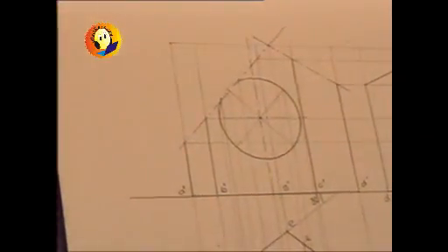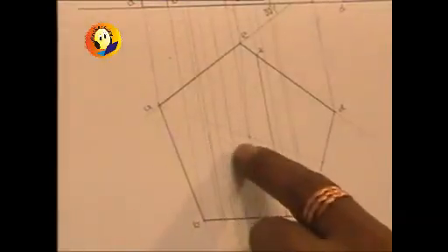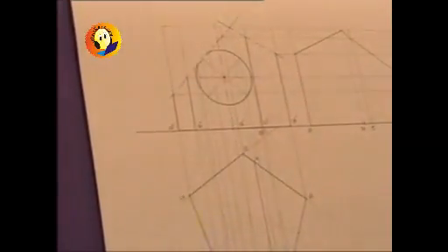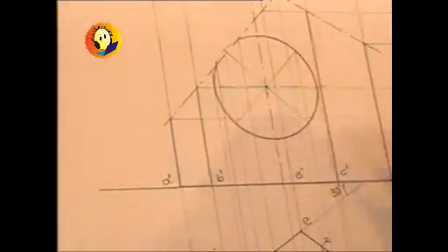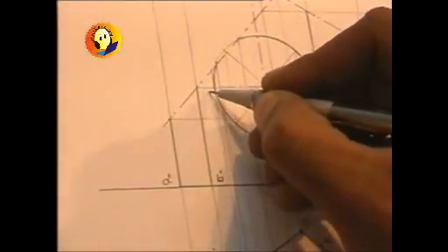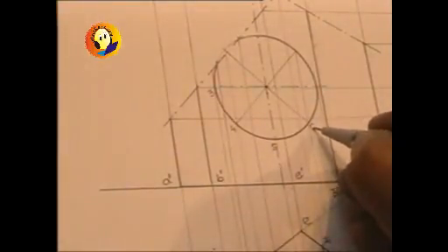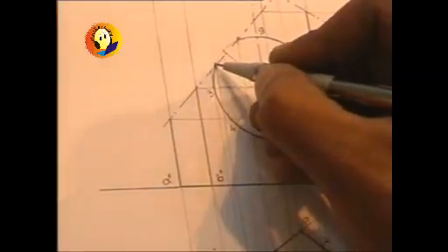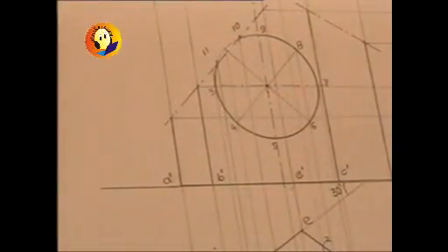And so the top view will now appear in this manner. So there will be so many points which will be coming, so many projectors which will be coming from the circle. Of course, we are required to name all the points of the circle and then name those same points even in the top view. So let us start numbering them. We have already used 1 and 2. So this is going to be point number 3. Then point number 4. Point number 5. Point number 6. Point number 7, 8, 9, and the 2 points of the cutting plane are respectively 10 and 11. Now to get those generators in the top view.